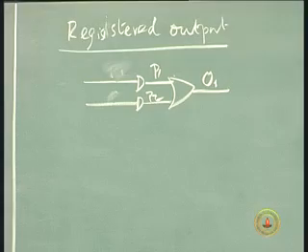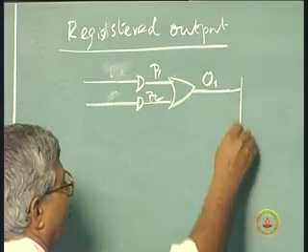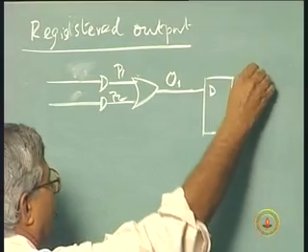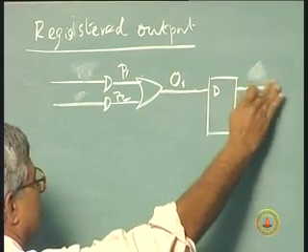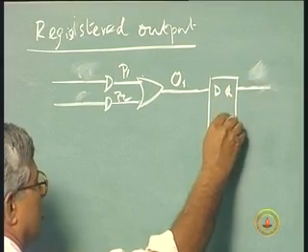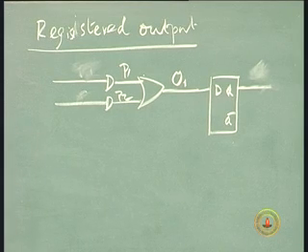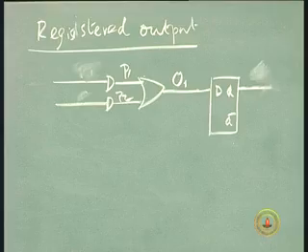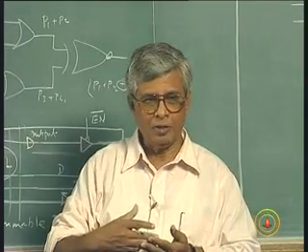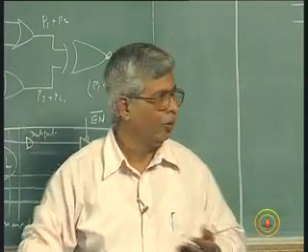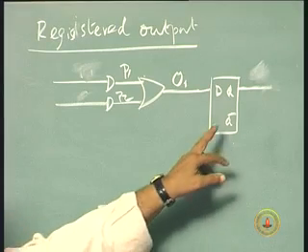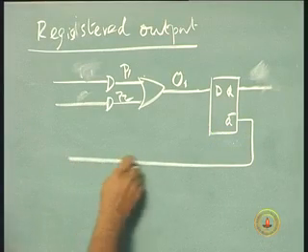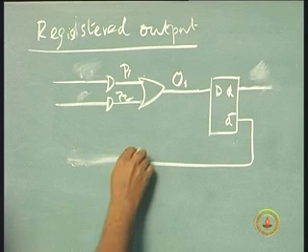So, that I can do within the chip itself. So, if this is my D flip flop as an example, this is my output function Q, and this has to be used as a steering input also for the next. See, state variables also used as inputs, is it not? Present state variables are the inputs to the next state. So, I want the output of this also fed back for available as inputs.